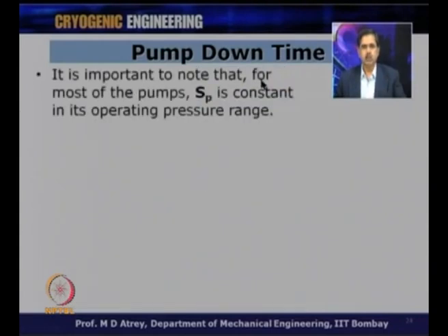It is important to note that for most of the pumps, Sp is constant in its operating pressure range. This is a fair assumption: if I have a particular pump, it has its own pumping speed, and this pumping speed remains fairly constant from when you keep the machine on, over a period of time. So, for a given pump, pumping speed remains constant. That means Sp is not a function of time.